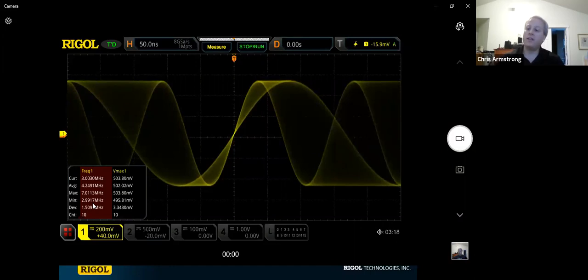So I guess the way to think about it is in terms of our technology, right? The 5000 is the entry point for our custom ASIC front end, which gives you, I think, the latest technology and some really nice capabilities and features. We're talking about 100 million to 500 million points of memory depth, 8 to 10 gig samples per second, and a great UI. It's all touchscreen and has all the functionality you need.